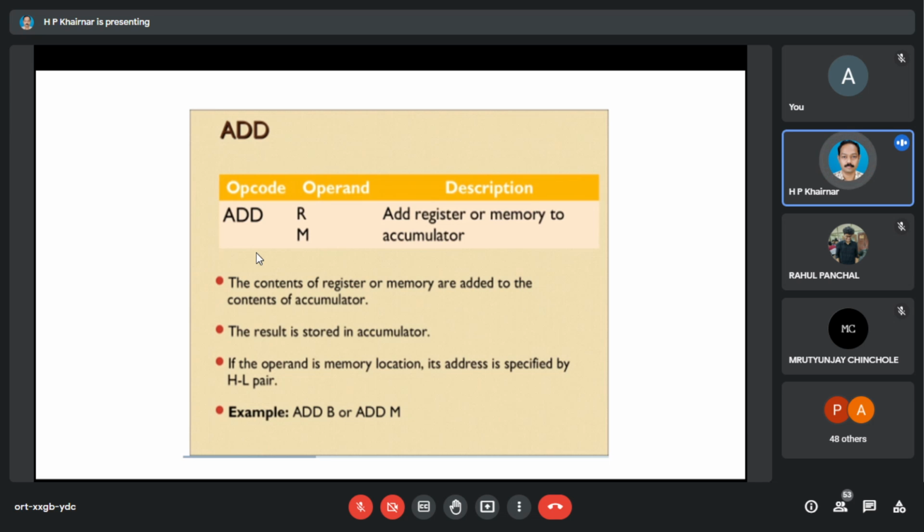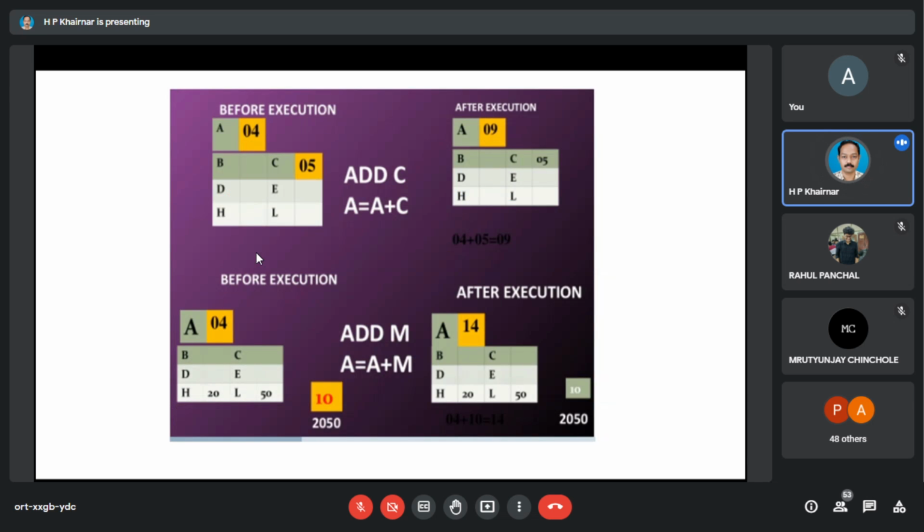Yesterday, some of you came and saw how the opcode gets selected. You have got the soft copy of the opcodes also. You can find out there what the opcode for ADD B is. ADD B is for you to understand for programming purposes, but the microprocessor doesn't understand it. It understands only the hexadecimal opcode, and some number is there for this ADD B. That number you will be typing on the keyboard. This is how entry of different opcodes will be done.